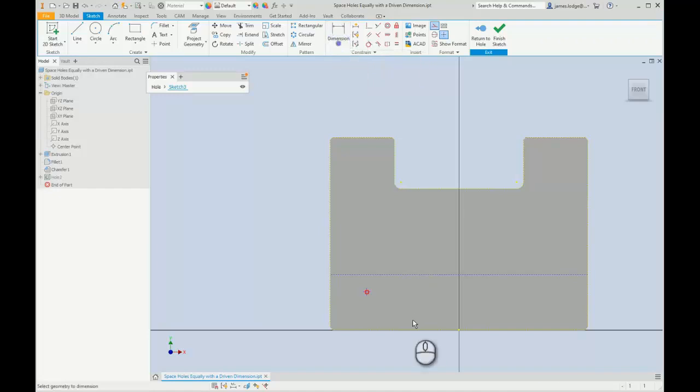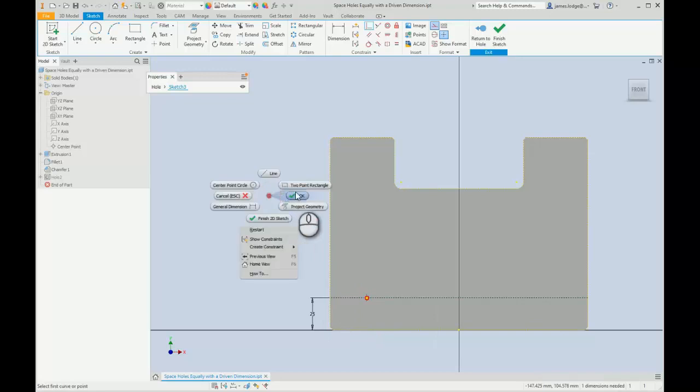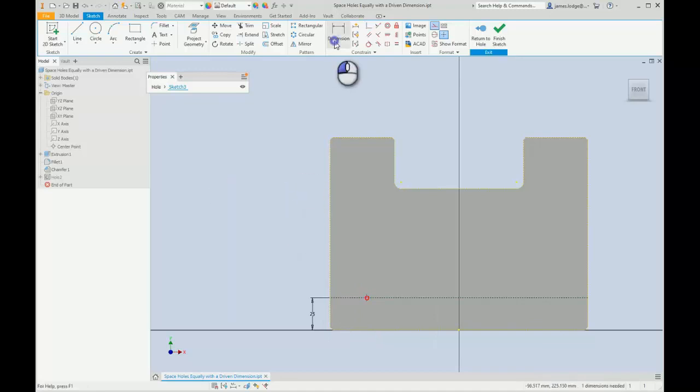I'm then going to just very quickly place a dimension here, because this will allow me to manipulate the positions in the y-axis should I need to, and then use my geometrical constraint to place the point for the hole onto my construction line. I'd then like to ensure that I've got an offset. I'm going to call this dimension offset 1, which will be equal to 10 mil. Okay, so that's that first hole positioning fully constrained.